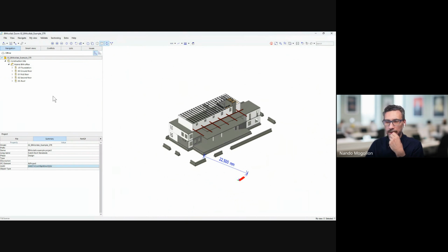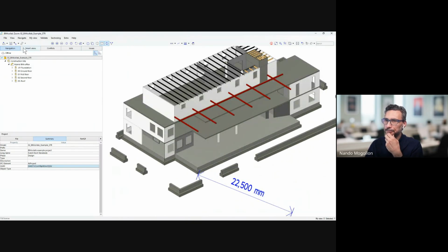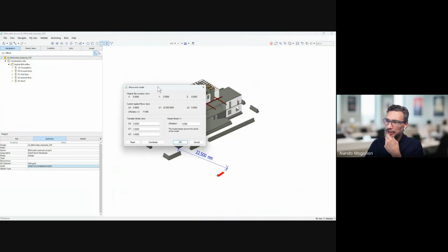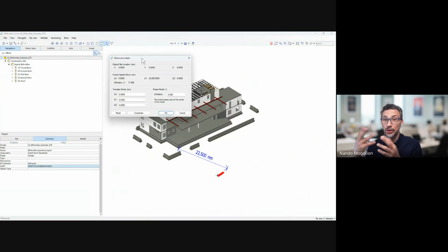I may not have a model right now because this model is not geolocated, but I'll tell you what, I'm going to give you the example anyways. Sometimes when the models are geolocated, the location might not be super precise, and that's going to result in some minor annoying discrepancies. If that's the case, but you know that the models have the origin in the same place, so the actual Revit origin and ArchiCAD origin are the same, you can revert the models to their original coordinates,